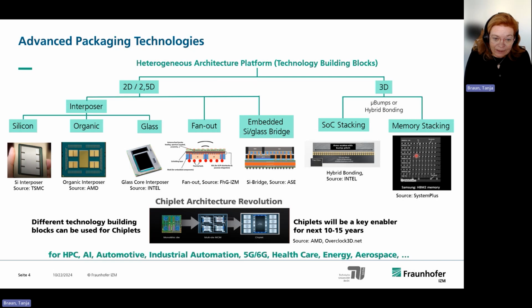And I think what we see at the moment is also a little bit how to extend maybe the organic solutions. Of course, we see a lot of progress in organic interposers, substrate technology. We see glass core substrates, which in the end also is maybe an extension of organic interposers, because we use a glass core with organic ABF layers as RDL layers on both sides. So there is also a lot of technology from pure organic interposers included, and we have fan-out also as an organic solution, maybe combined with a bridge for very local high density routing.